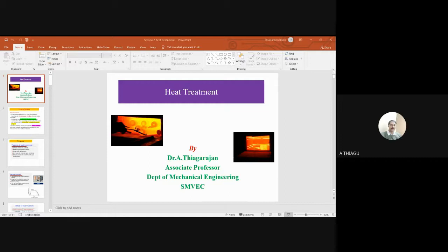What duration can I prefer? Only 6 hours is sufficient, and the corresponding temperature will be 900. Suppose I want to coat 2.5 mm thick. The temperature I suggest is 950 degrees, but the duration will be 16 hours. So based upon the thickness, your time will be increased. That is very good information to collect from the pack carburizing process.